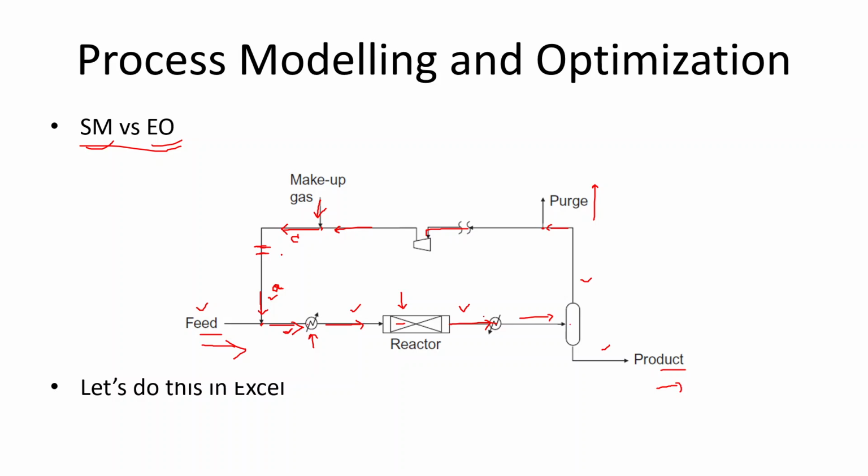There's direct substitution, where we can simply say, okay, this is the calculated one, so I will use this number in here. Then you have to repeat the calculation again. So if we have a fixed feed, and then a calculated value over here, you calculate this, calculate that, and so on, and then compare the new calculated value with the previous calculated value. Are they the same or not? If not, then we have to repeat the sequence again. That's one approach.